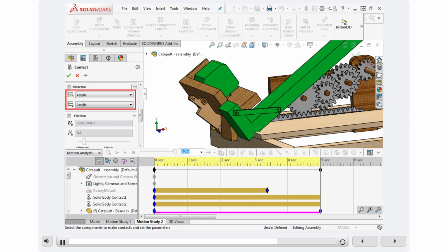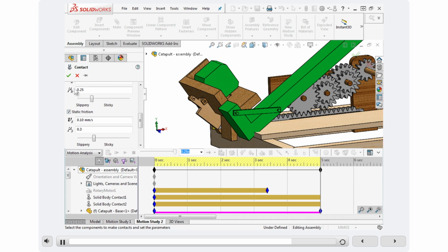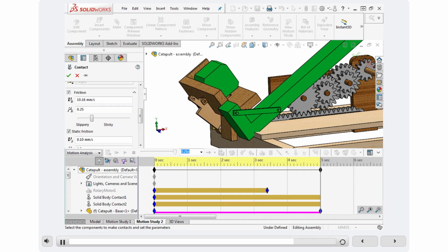Under Material, select Steel, Dry. Make sure that friction is checked. Uncheck Material. Note that unchecking Material opens up the friction dialog fields for editing. The contact characteristics in elastic properties, determined by the selection in the Material dialog, remain unchanged.